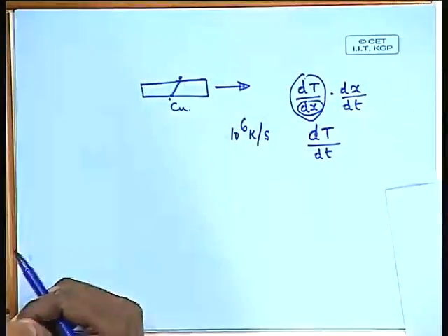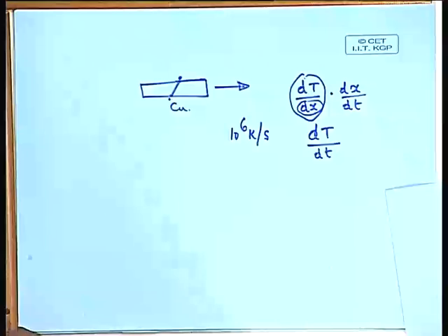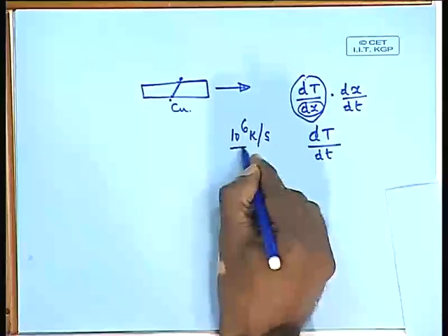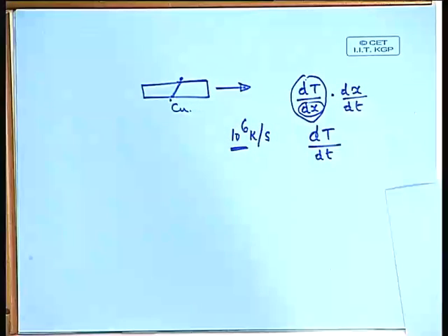Okay, so I cannot really say aluminum I will start pouring from 10,000 degrees centigrade, nobody would do it. So as a result the delta T is something which you cannot really vary. The only thing that you can change is dx, and that's what is here very small, and because that is small you are able to have high dT by dx, and which is what giving you this high cooling rate.